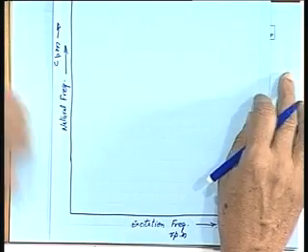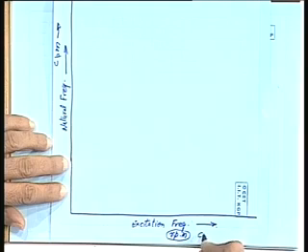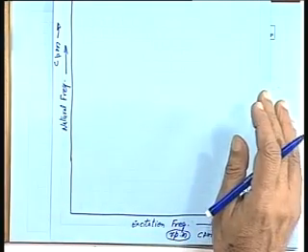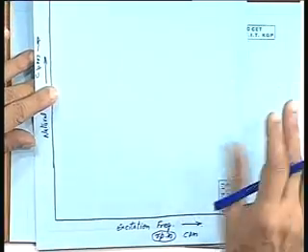Okay. This is the trend, but this is also cycles per minute. When we say frequency in cycles per minute, it implies shaft RPM, the external exciting frequency. It can be anything, whatever the logbook will give you. In fact, with experience also, when we feel the vibration level is increasing, we try to adjust the RPM only.